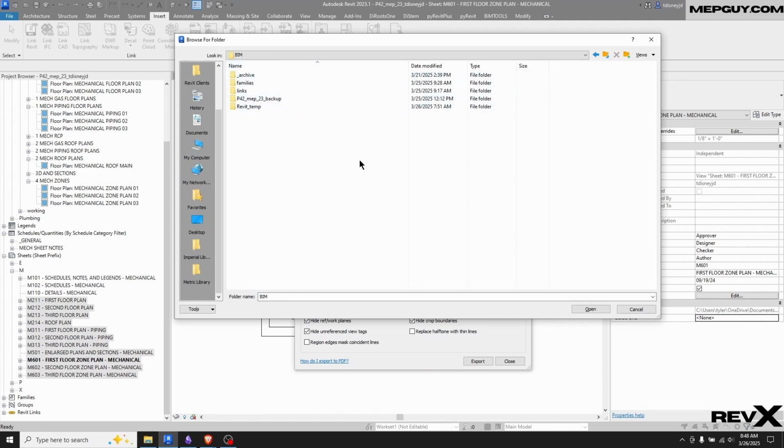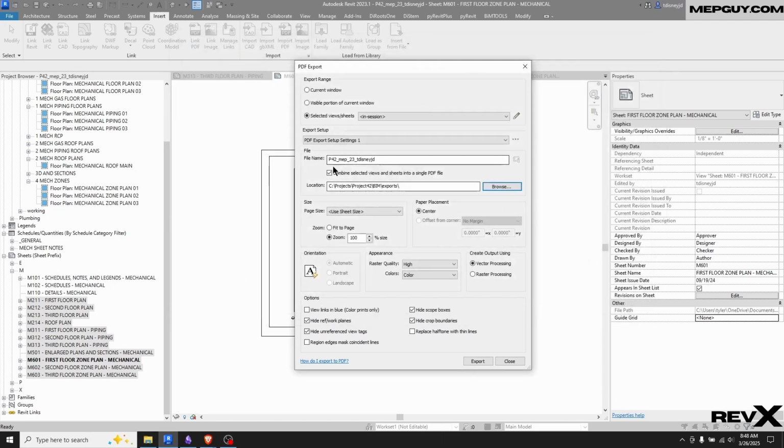Bim. So you might want another folder. I like to have another folder in here called exports. Anything that I export out of the Revit model, whether that's sheets, FBXs, IFC files, DWGs, anything, goes into this exports folder first before it goes anywhere else.